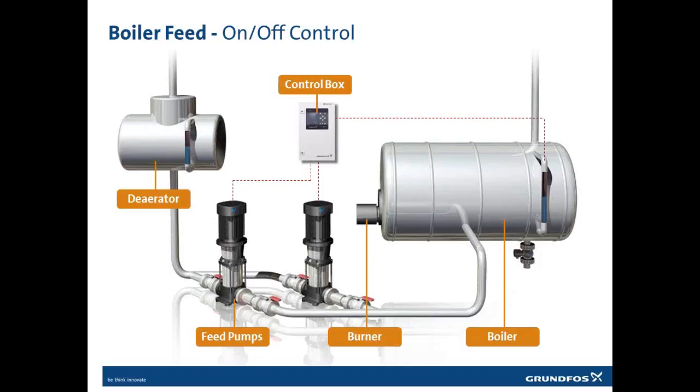When we start the pumps, they run full speed and simply take as much water from the deaerator and pump it into the boiler as fast as possible. That means the boiler receives a relatively large amount of cold water, which gives mechanical stress in the boiler, and it will decrease the natural boiling of the water in the boiler, because the water is cooled down.